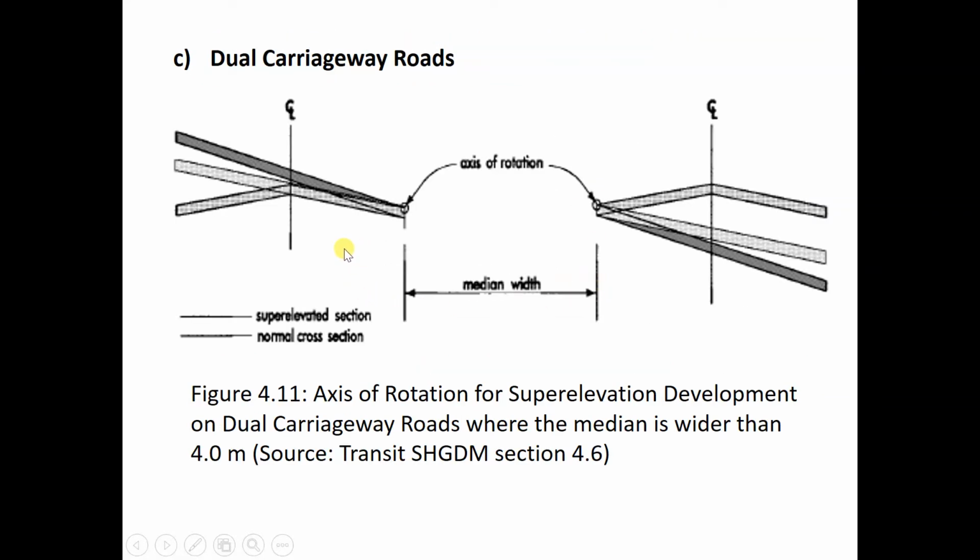For certain roads, the dual carriageway, they have this normal camber. It slopes both sides, so they have a drain on the left hand side and a drain on that side. But when there's a turning right, the things are going up as well. From the right, the outside lane will go up to level and then go further up, super elevations.